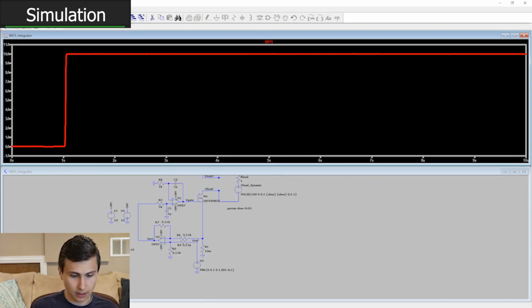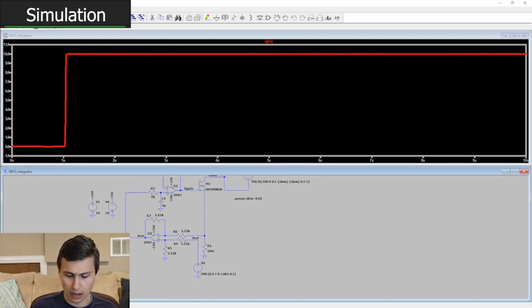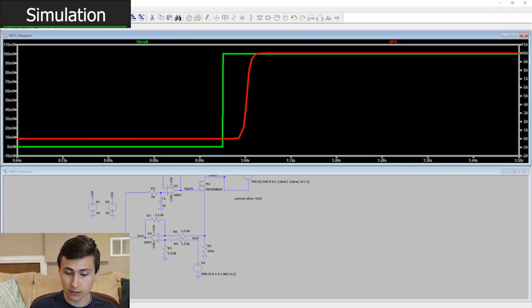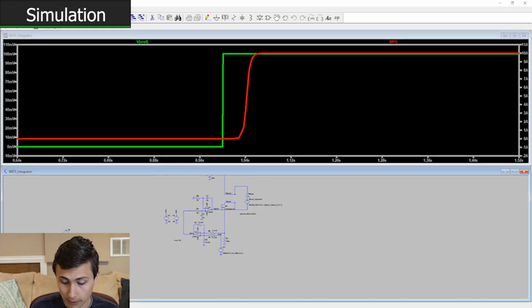Excellent. So yeah, how I feel about the step response is it's a little bit slower than I would like. I wish it would respond more accurately. Like if we were trying to do an impulse response with a very short duration, I don't know what kind of control you'd want to do, but if you were trying to do PWM control, this would definitely limit your PWM duty cycle because you need to wait for your regulator to get up to the set point. However, there's no overshoot, so if you're pretty sensitive to overshoot, that might be just fine.